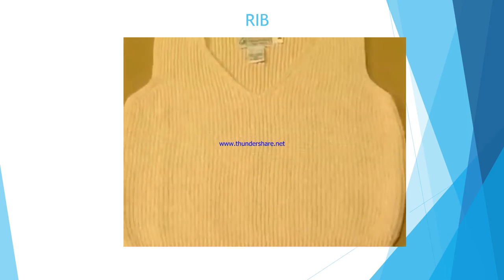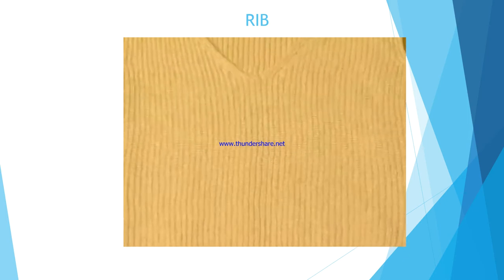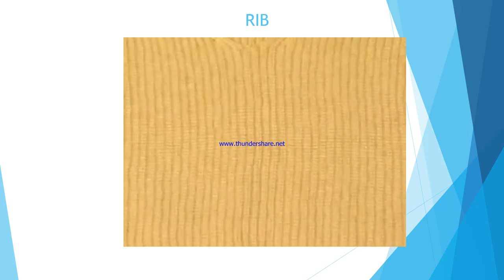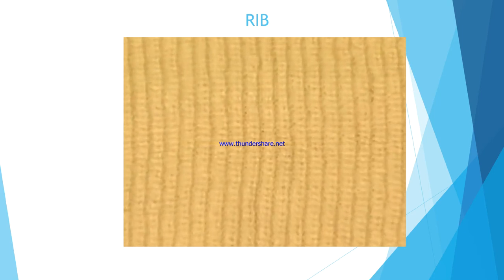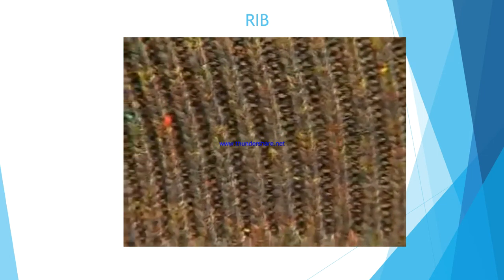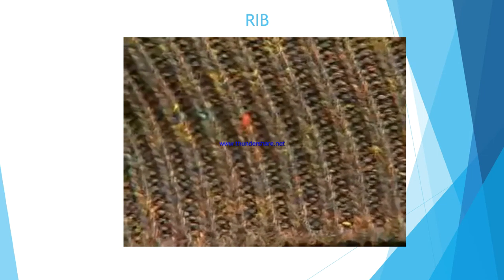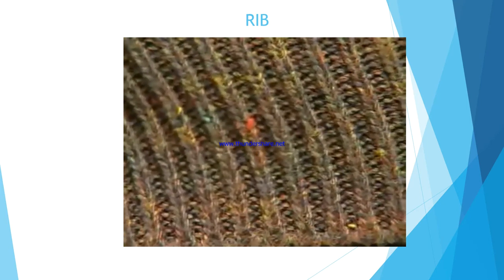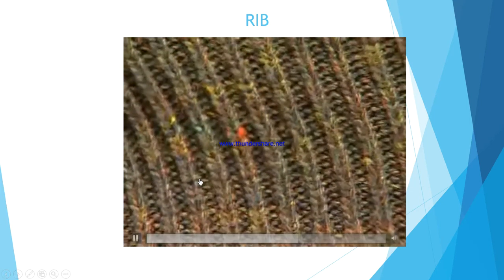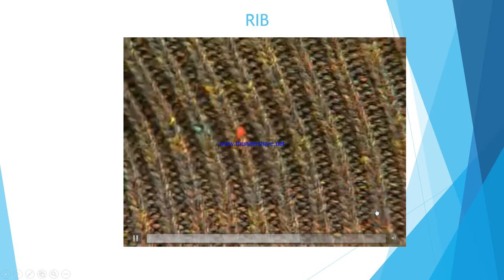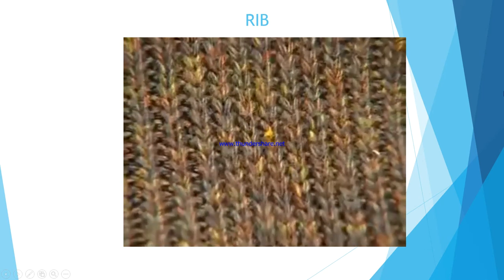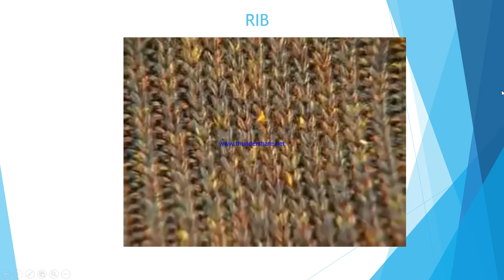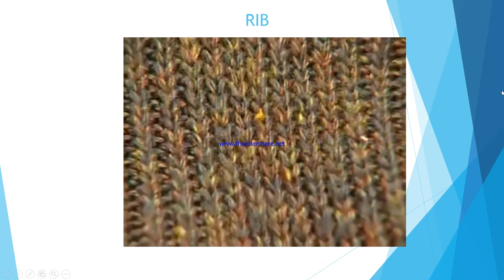Because basic rib knits have alternation of face and back wales, the structure can easily be stretched. In the normal relaxed state, the back wales hide behind the face wales. When stretched in the width, the structure opens like an accordion, resulting in more stretch than single knits and other double knits. The back wales now become visible. When pulled in the length direction, the back wales move behind the face wales and the fabric becomes more narrow.